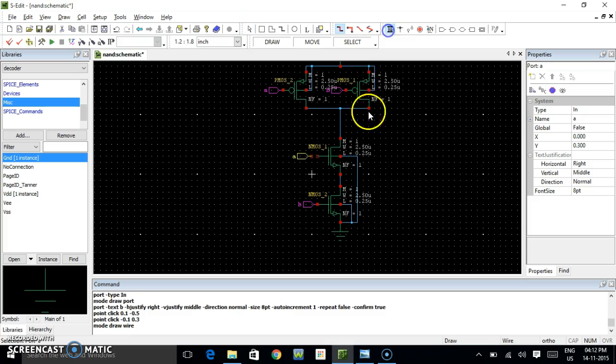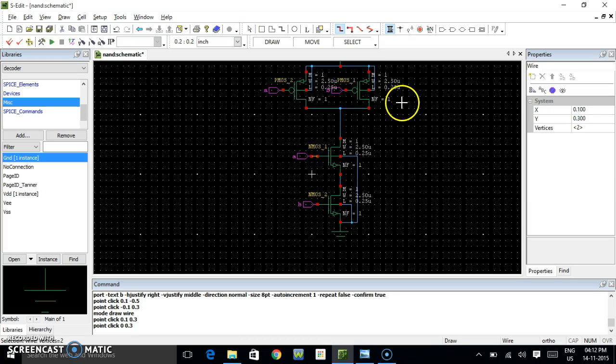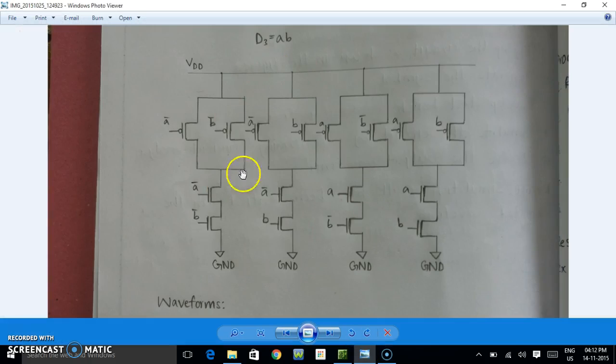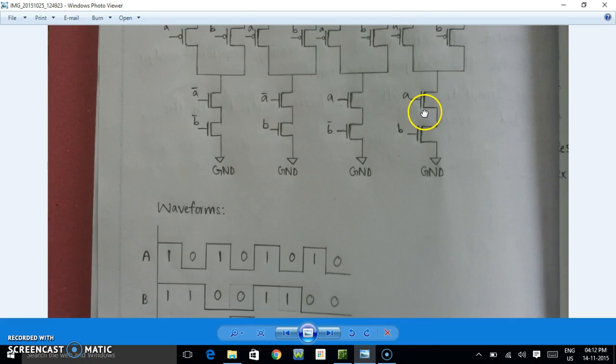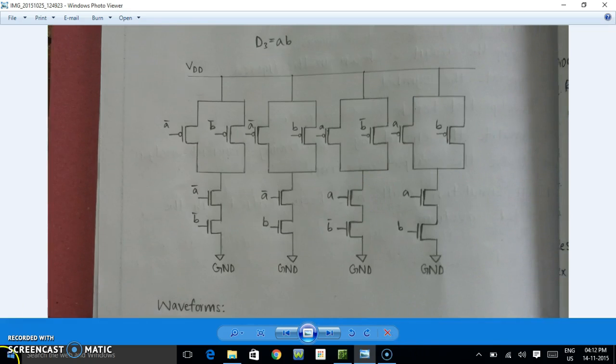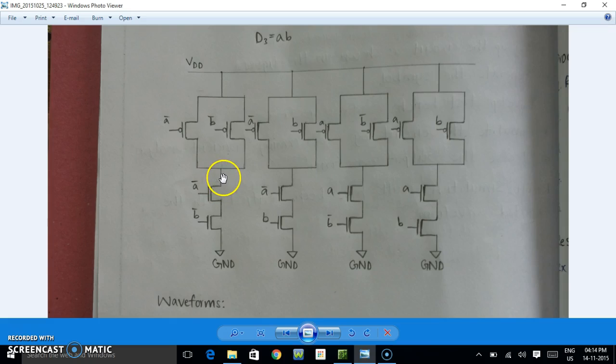The reason being that, wait, I'll show you the reason for that. Here we do not have an output port to this because the output should actually be somewhere here, I guess. Or wait, why don't I have an output? Okay, I'm sorry, actually there should be outputs here as well, which I forgot to mention. Here, and an inverter is supposed to be connected here, which would be our Y3 if you want to call it. This would be our Y2, Y1 and Y0. If Y2, Y1, Y0 and Y3 are the outputs, so there should be an inverter connected here, here, here and here.